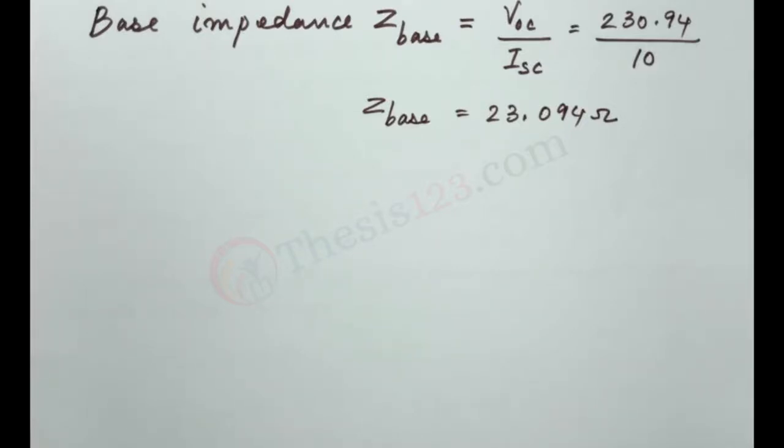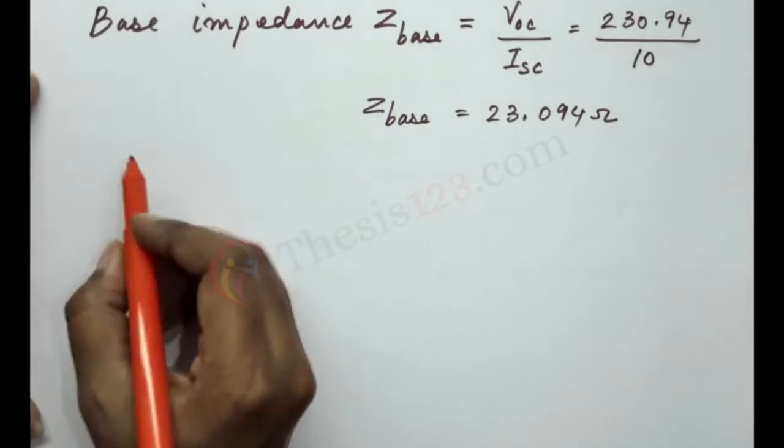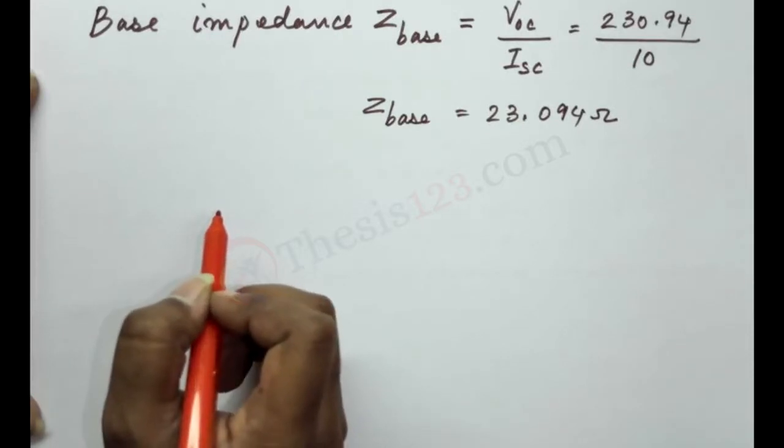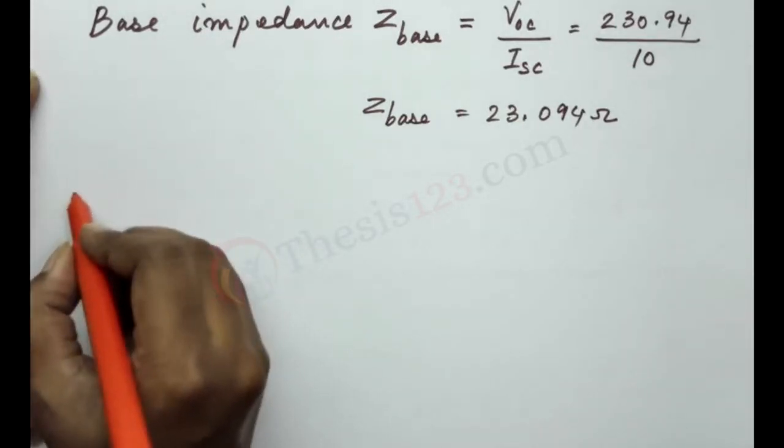Okay, so the question tells us to find out the synchronous impedance at rated voltage, right? In order to do that, we will have to take the ratio of the short circuit to open circuit portion, which is actually called the saturation effect. So this has to be considered. Let's be very careful with the ratio here. So the actual value of the synchronous impedance, ZS, at rated voltage is what we will have to find. So please take a very close look at this. Let me write this down. Here we are going to write down the ratio of the short circuit to open circuit